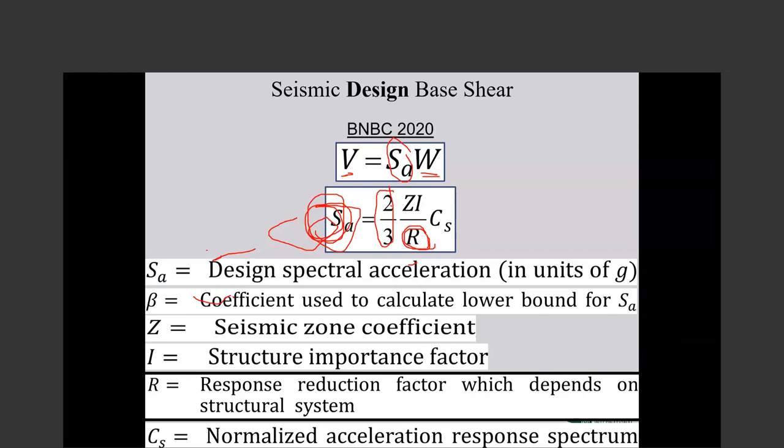So what we did, for example, for reinforced concrete, we calculated the demands based on simple modeling, simple analysis, elastic models. But during design, we multiply the moments by 2 factors, one for the P small delta and one for the P big delta effects, C1 and C2, as they are famous for. So traditionally we do that.